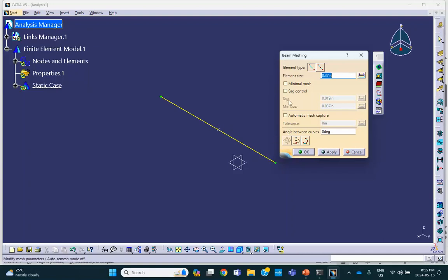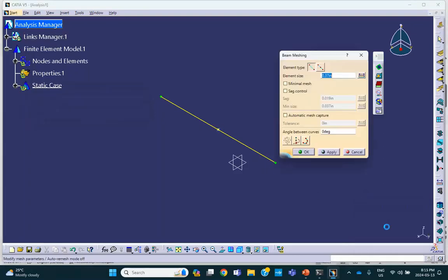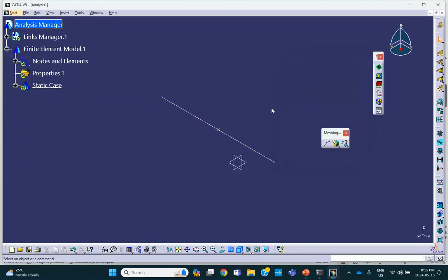The only thing is that when I clicked on this thing, let's use a different tolerance. So I'll make it 0.0001. That is the point. Very small tolerance, because it didn't like it when I put 0, and then I say okay. As simple as that.